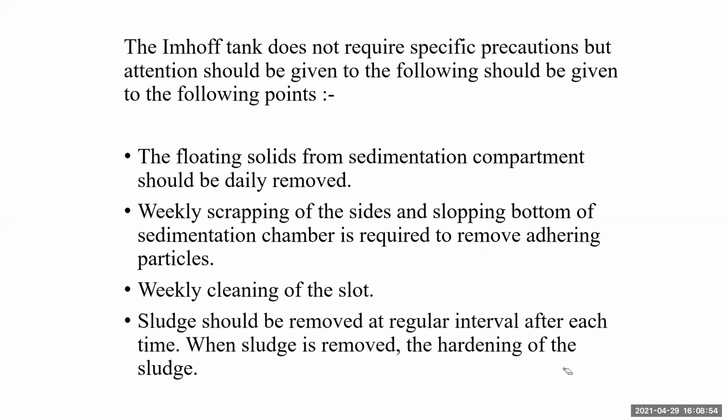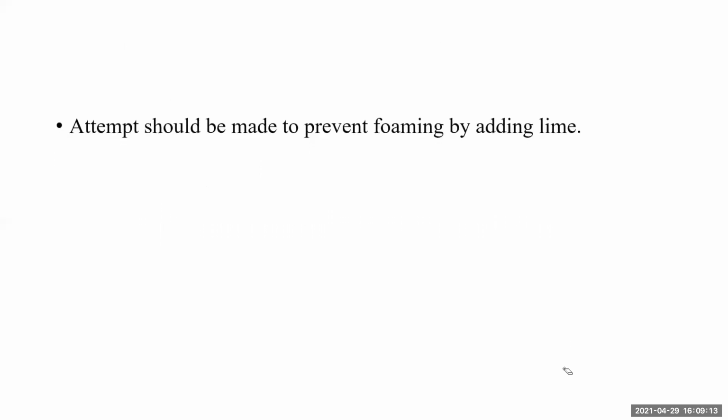The slot, the hole in the upper chamber, has to be cleaned weekly. Then sludge that settles down in the lower chamber has to be removed at regular intervals. If the sludge is not removed, hardening of the sludge may take place, so we have to remove it regularly.